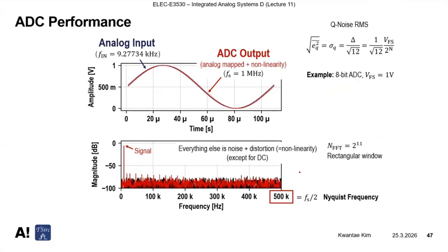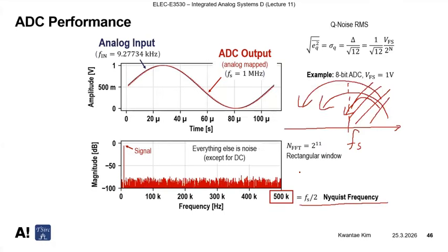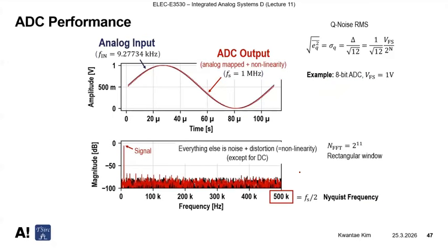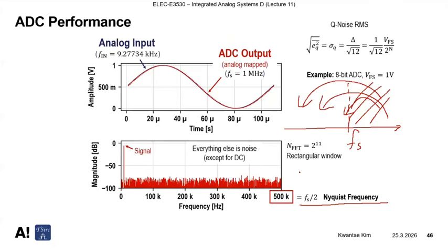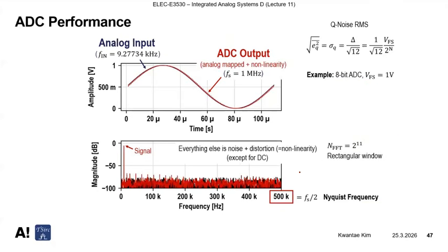So after adding nonlinearity, what I did is I just used the ideal ADC, ideal DAC, and this is an output domain waveform which is analog, mapped from the ADC output, digital to analog mapped. And I also added one transmission gate before we quantize to the analog to digital converter. Then you get non-linearity, as we discussed. Then you can see that compared to this case, now this red curve becomes the black curve.